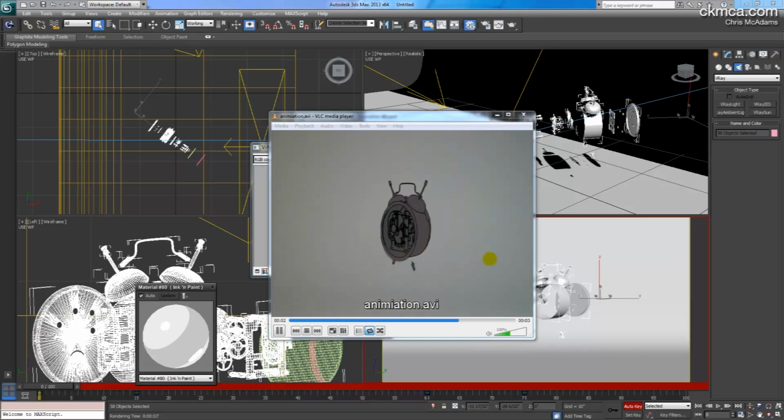We brought it in from Rhino. We grouped everything by prefix name, applied V-Ray materials to them, set up a backdrop and camera with lights, did a quick test render using SolidRocks, which you can find the link to in the description below, and then keyframed everything. So this is just the basic workflow. You can imagine you can go a lot more complex. We can scale and change transparencies and things. You could move the camera around or aggregate this. You could take it in 100 different directions, but this is just kind of the basics.